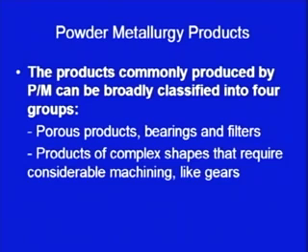If we want to make gears using any other manufacturing process like machining or casting, they will subsequently require a number of machining operations. Machining will result in wastage of too much material. If casting is done, the quality that we may get may not be according to our desired levels. So, subsequent machining is required there also.